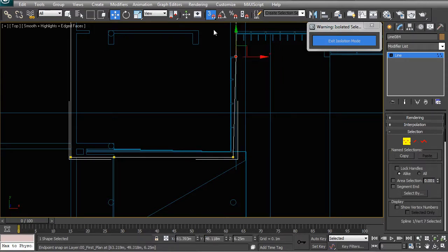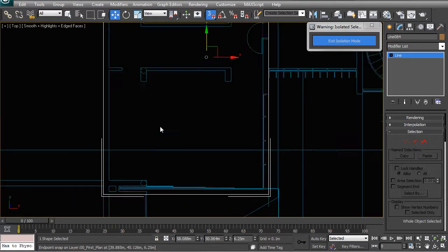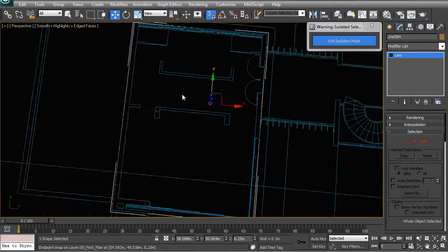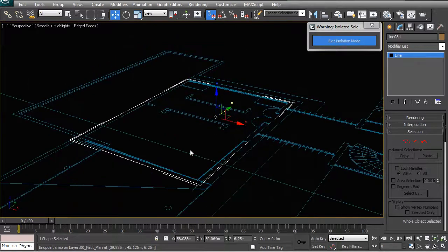And I'm going to do the same thing for the X here. I'm going to take this, press copy, choose the other vertex, and paste and enter. So that will basically manually copy paste the X and the Y coordinates from other areas on the wall. And this is something that I do quite often in my workflow, where I just make sure that every point is in the right X or Y or even Z coordinate.